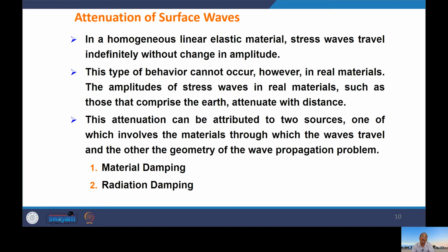So if you consider the ideal condition that soil consists of a homogeneous material and it is linear and elastic also, if this condition is satisfied, then we can assume that the stress waves are traveling without change in amplitude. But this is not the case, and this type of behavior cannot occur in real materials. The amplitude of stress waves in real materials, such as those that comprise the earth, attenuates with distance.